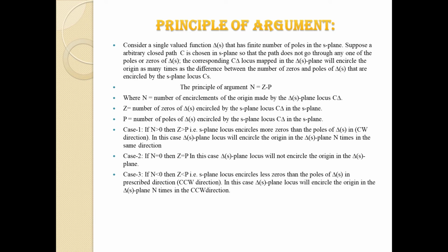And the next one is the principle of argument, that is Cauchy's principle of argument. Here we are considering that delta S is a single valued function, and single valued function means for each point in the S plane there exists only one point in the corresponding delta S plane, which is a plot of the imaginary part of delta S on the y-axis and the real part of delta S on the x-axis.